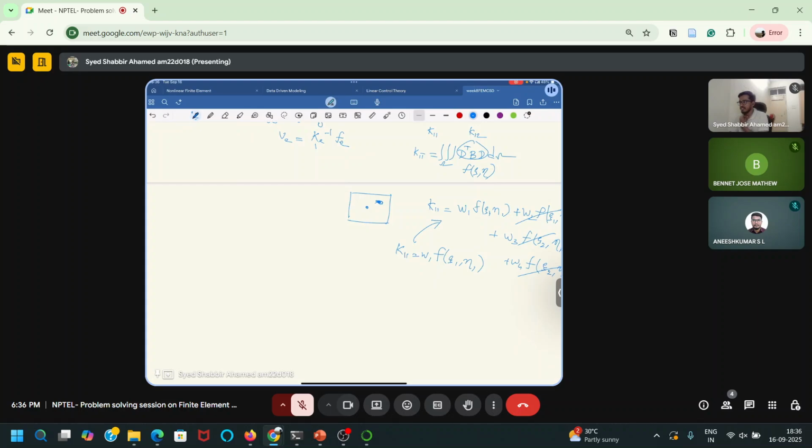Then we have also seen some explanation about the patch test. The patch test is a test to see if you can get the convergence for your problem, instead of solving the whole problem.